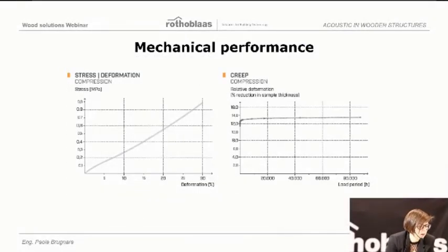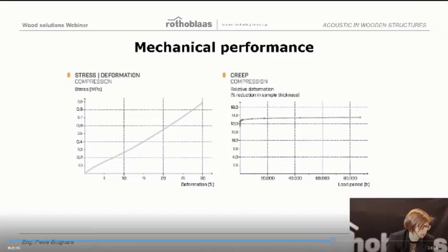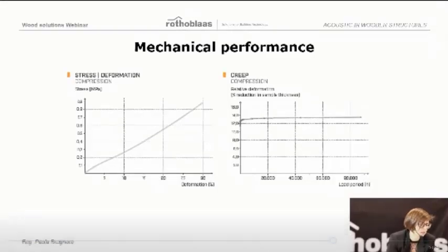So from a mechanical point of view, we have chosen a material that does not have creep. As you can see, after the first deformation, which is due to the load applied, we will not have an increase of the deformation. And then we have also chosen a material that has a very linear deformation. This is very important, because if we don't estimate the load in the proper way, we need to make sure that the profile will not be affected by a different load. So of course acoustic performance will change and so on, but